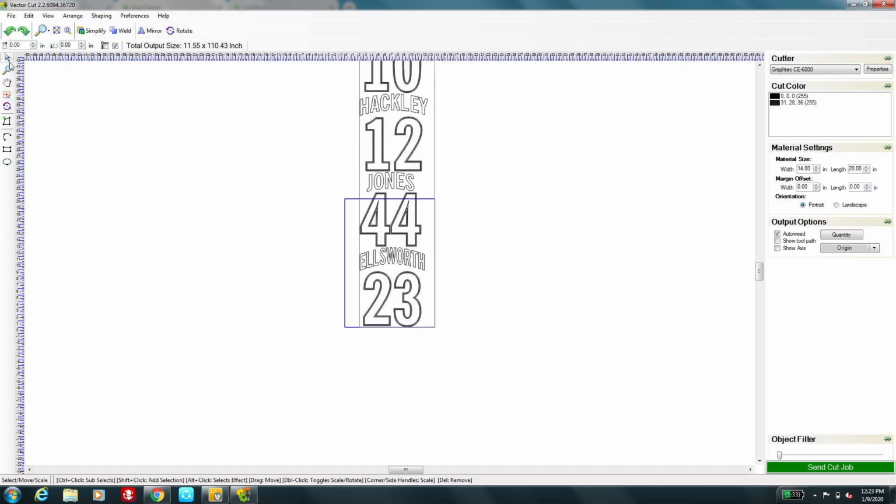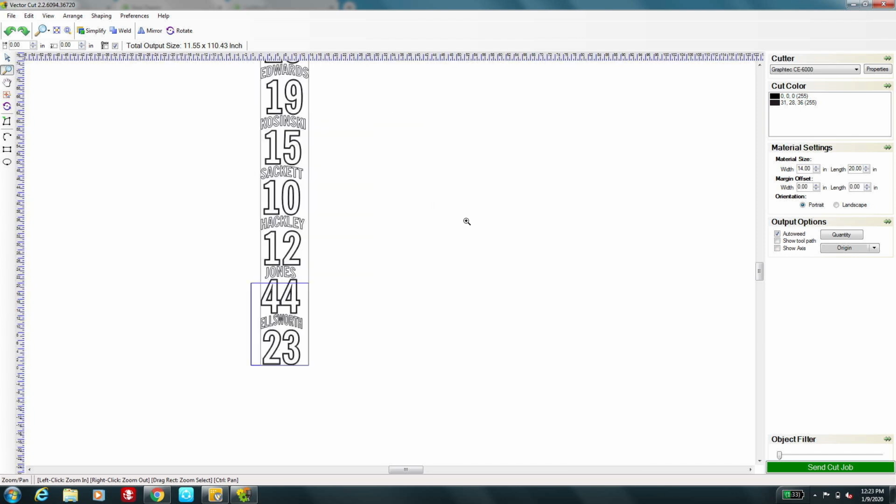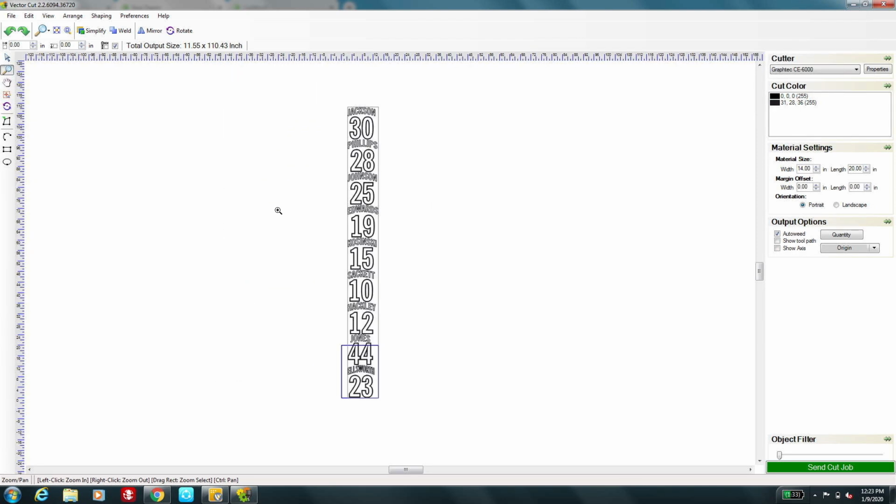So as you see here, when you open it into your cut driver, I'm going to zoom out a bit, it has created all of my combinations. So you can see I have my 14-inch wide material. In this case, I'm going to change the length here. For some reason, it did not take, so I'll report that. Change it to the 99 that would allow me to do. I think I can even size it above. We just don't want you exporting super large files. So I'm going to make sure it's longer than the names I have, otherwise it'll cut it off. It's very important that your page size exceeds the length of your names, and it'll create those combos.